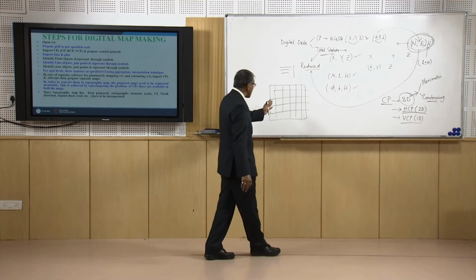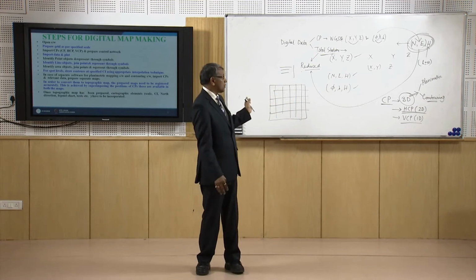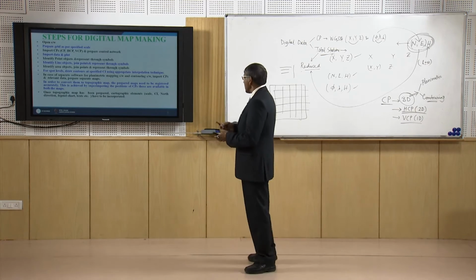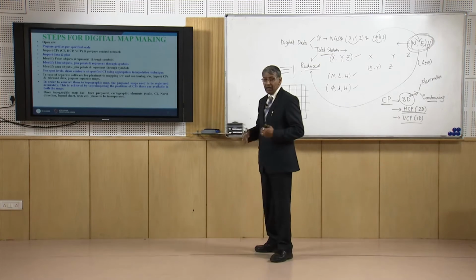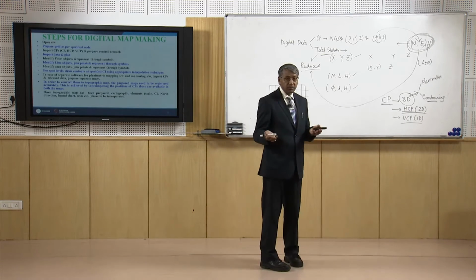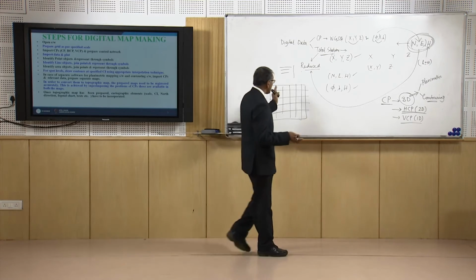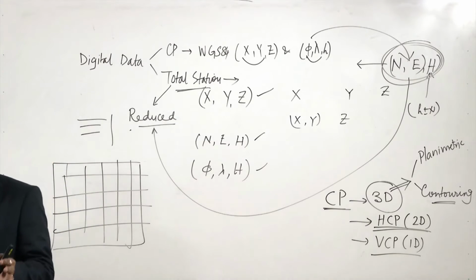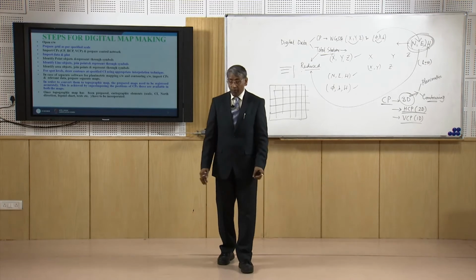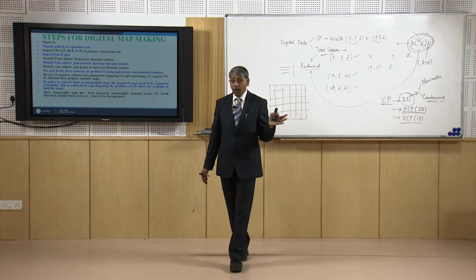Now we can check whether the positioning of the control points matches what we had considered in the field. If it is fine, then we should proceed forward. If it is not, then we have to find out if there is any mistake, and those mistakes have to be taken care of, because it is the network of control points which provides the base from which the whole mapping process will carry forward. So there should not be any mistakes in plotting the control points or their mutual position.